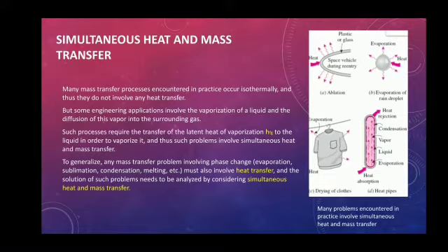In general, any mass transfer problem involving phase change, such as evaporation, sublimation, condensation, melting, and others, must also involve heat transfer, and the solution of such problems is to analyze them considering simultaneous heat and mass transfer. So we can see in the picture many problems encountered in practice involve simultaneous heat and mass transfer.